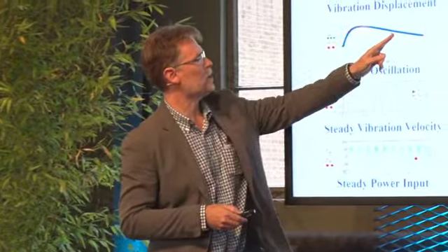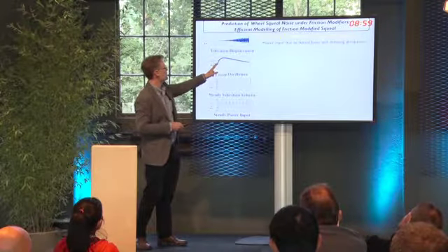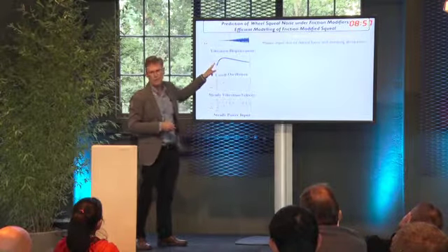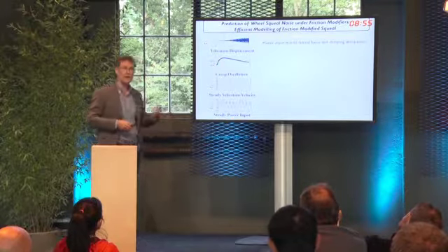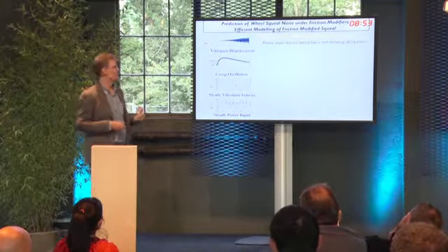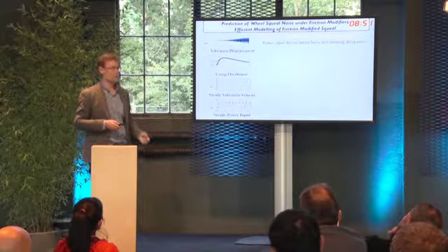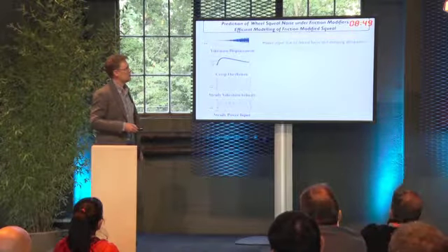So to cut a long story short, in order to predict this limit cycle amplitude, we looked at the problem in terms of an energy balance. What happens is the squeal vibration grows until the creep oscillates over to the positive side of the curve, where energy is actually dissipated along with the damping in the vibration mode.